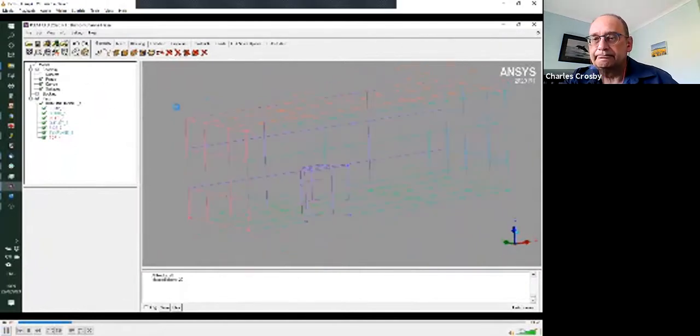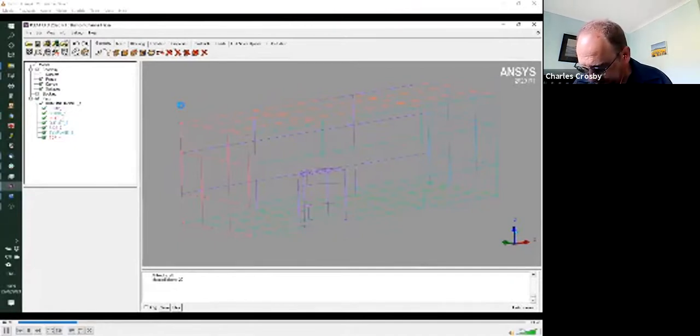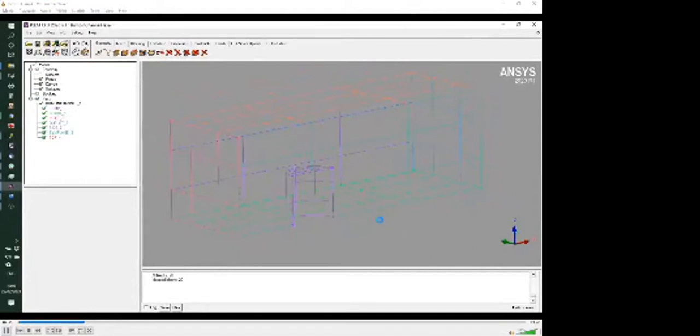So we take it back to a wireframe display. We've got different ways of meshing this. I'm going to demonstrate two of them. One is to make use of multi-block structured meshing, and the other one will make use of unstructured tetrahedral meshing. We're starting off with exactly the same geometric model. The geometry is represented as a sequence of points, lines, and surfaces. Because it's a solid model, there's effectively a solid volume contained between these surfaces, but ICEM Hexa is not particularly concerned about that.